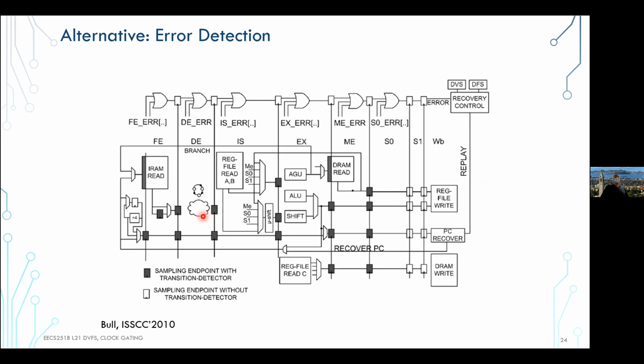Yeah. But couldn't you violate the hold time if you just simply scale the VDD first? It can, but you should be set. This goes back to how you're characterizing your whole circuit, right? Hold time doesn't have anything to do with what the cycle is or what the frequency is, right? So if you characterized your circuit for highest VDD or let's say lowest VDD, you should be set, right? Unless there's some weird scenario, which, looking at these delay profiles that we saw shouldn't be there, that somehow for some voltage in between, you get a hold time violation. Let's say a clock register mismatch versus some short wire delay or simple logic gate mismatch.